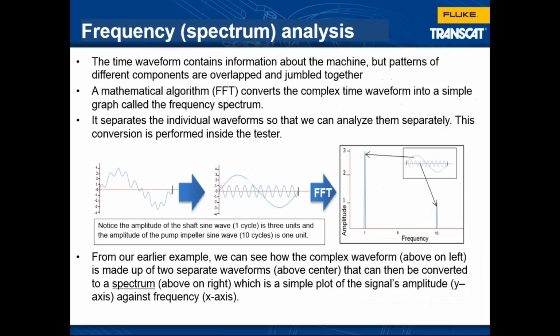So the question is, without being a vibration expert, how do I read these things? Well, and again, I'm not going to get too deep into this, and don't worry, the vibration tester actually does this for you, but we convert it to something called a spectrum, and you'll hear vibration experts talk about the vibration spectrum. Basically all we do is take this complex waveform and separate the individual waveforms into a simple XY plot. So you can see the plot over on the right hand side is showing our 2 sine waves.